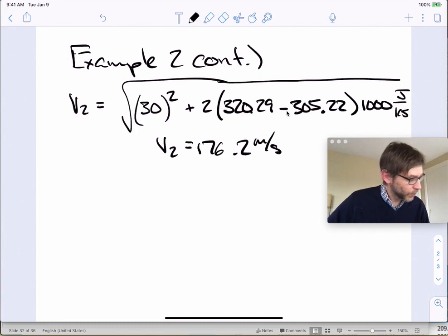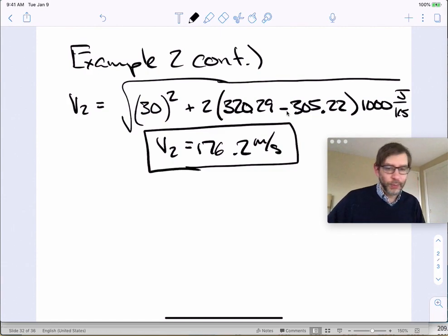All right, 176.2 meters per second. Okay, so that's pretty fast. That's some pretty high velocity air. Came in at 30 meters a second, and it leaves at 176. Man, it really had a lot of clog in that tube, and definitely had a situation there. But okay, fine. Dropped a lot of pressure, and we added some velocity.